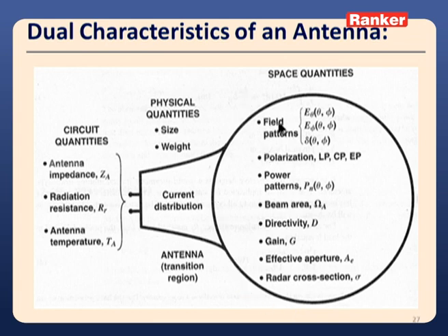The field patterns or the power pattern will be there. In the field pattern we are supposed to observe the electric field in theta direction, electric field in phi direction, and the phase difference between all these fields. And what are the different polarizations we have, like linearly polarized signal, circularly polarized signal, elliptically polarized signal, and a power pattern can be observed in the space.